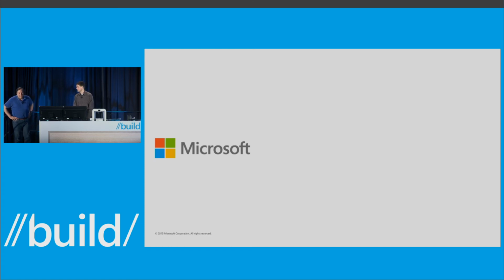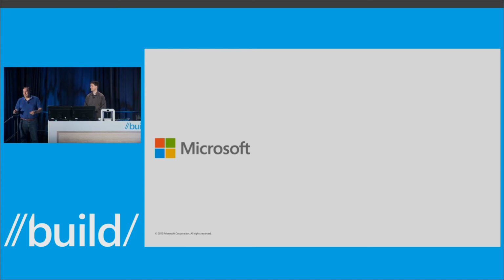Yeah, that is. In fact, that's one of the key things that we're putting into the material spec. It is not in the Windows 10 material spec, but it's not just about the material. That part is probably shrinkage, and so as some of the materials shrink, they suddenly don't fit anymore, especially with ABS plastic. So one of the things that we're talking about putting in the material spec and working with the print companies is what's the shrinkage, so that you could build it too big so that when it shrinks it's the right size. As far as being too big, I don't know what would cause that. That's a little interesting, probably just your printer is off.